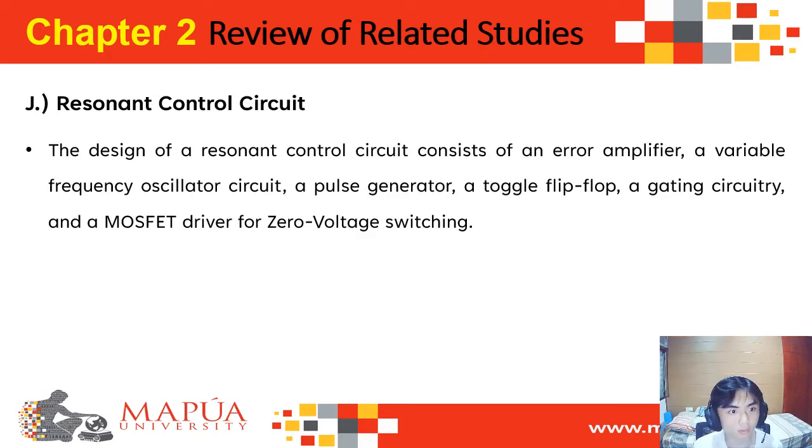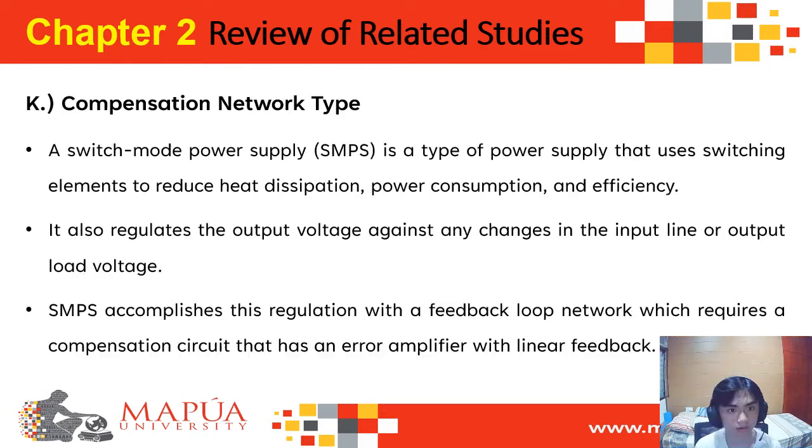Next is the resonant control circuit. The design of a resonant control circuit consists of an error amplifier, a variable frequency oscillator circuit, a pulse generator, a toggle flip-flop, a gating circuitry, and a MOSFET driver for zero voltage switching.